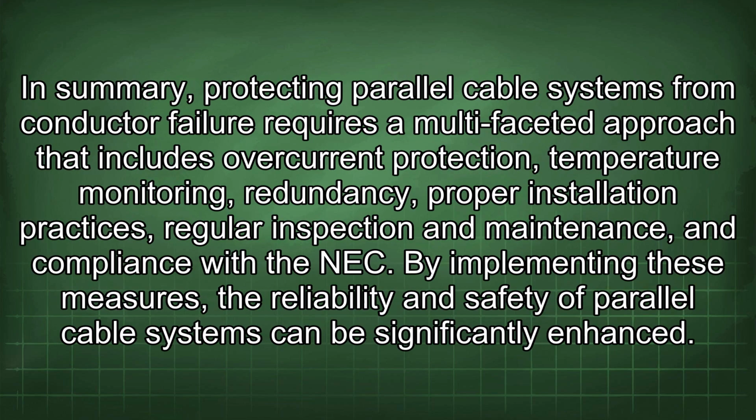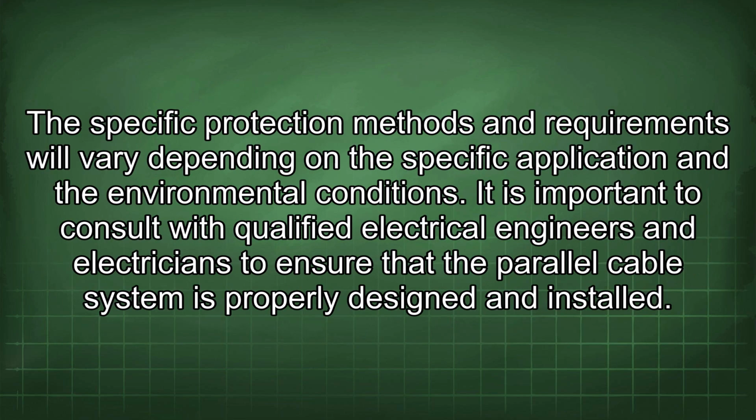In summary, protecting parallel cable systems from conductor failure requires a multifaceted approach that includes overcurrent protection, temperature monitoring, redundancy, proper installation practices, regular inspection and maintenance, and compliance with the NEC. By implementing these measures, the reliability and safety of parallel cable systems can be significantly enhanced. The specific protection methods and requirements will vary depending on the specific application and the environmental conditions. It is important to consult with qualified electrical engineers and electricians to ensure that the parallel cable system is properly